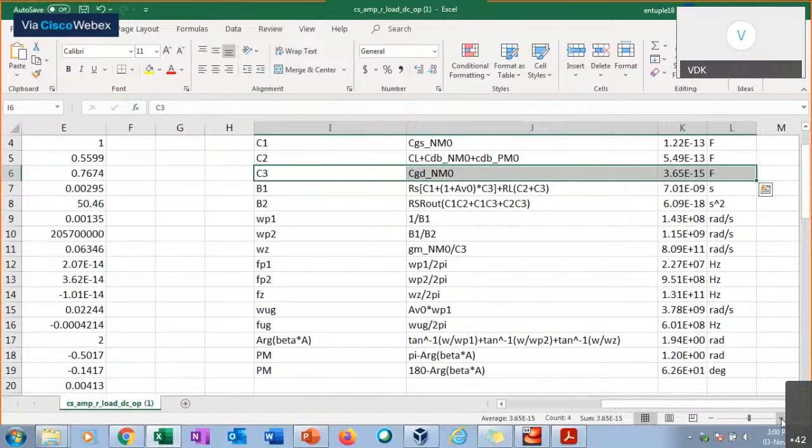Because this is a two-pole transfer function, please note that the input stimulus source has resistance which is reasonably large. So the circuit exhibits two time constants essentially, one for the input circuit, one for the output circuit. The input circuit time constant is given by the sum of the time constants associated with the capacitances at input as well as at the output.